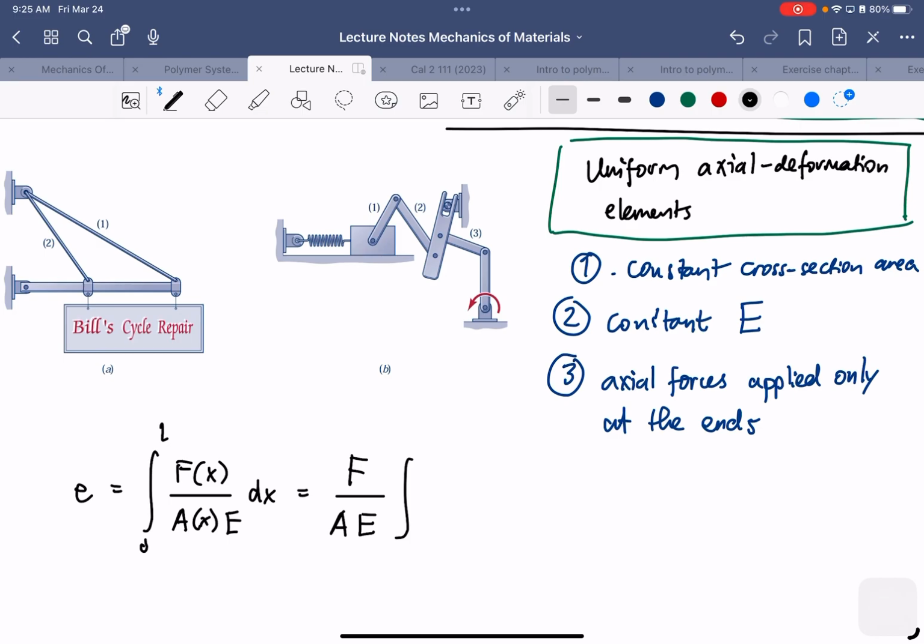So we can see that the difference is just on the dx. So as long as we know the length of the members, then we can simply write our formula. Or we could just simply, if started at 0, write that delta equals F L over A E. Okay.